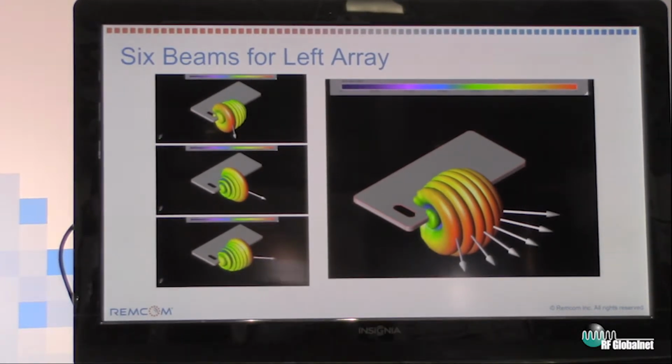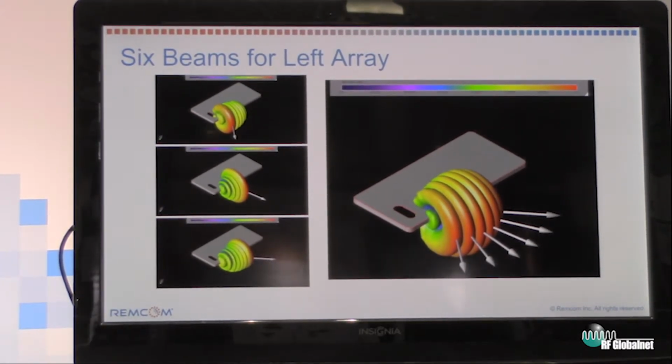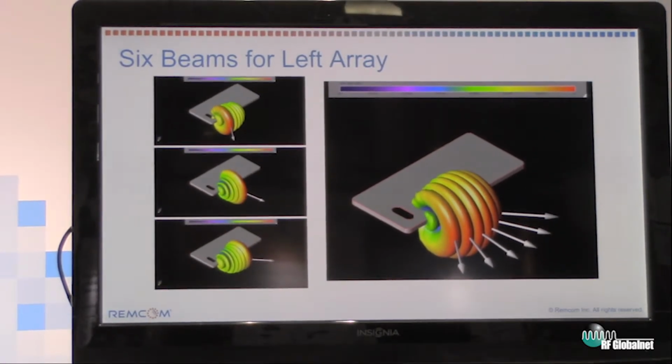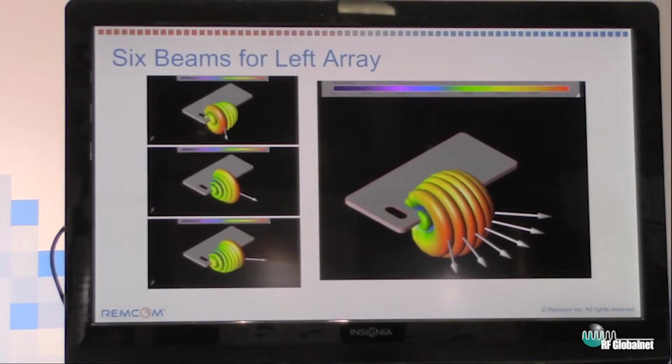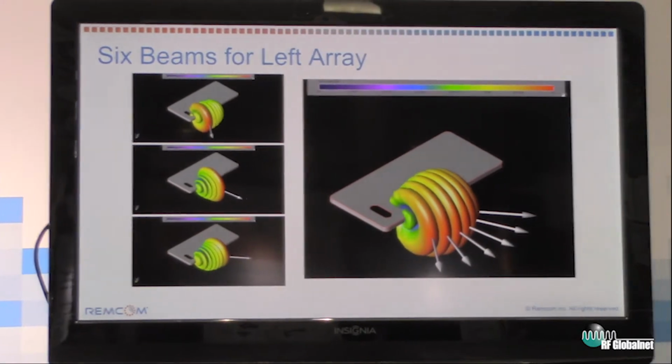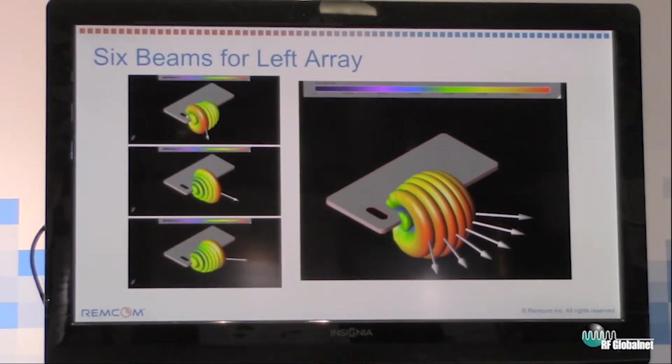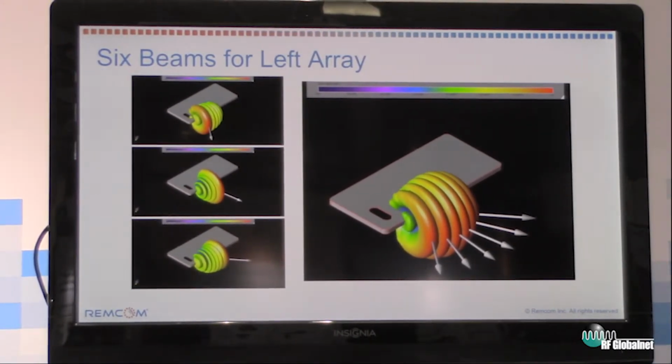And the trick here is to find a single metric that can be used to quantify the performance of this array. In traditional SISO antenna applications, engineers would look at half-power beam widths or total radiated power. Those metrics, however, get unwieldy when you try to analyze multiple beam states. So instead, we have developed a single metric that characterizes the antenna performance while considering all beams at once.